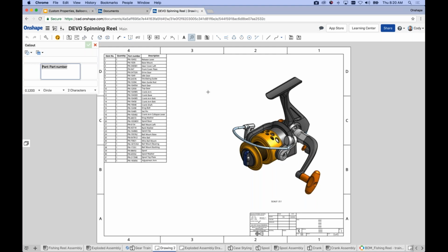And so by default, when you click balloon, right, the callout command, you'll see you can define what you want it to be, right? So I can go in and define item number, for instance, and define that as the criteria that I want for my callout. Now, you may have seen part number or description or revision, right? It really depends what your goal is there. But then from there, it's really just a process of left click, left click, left click. And all I'm doing is left clicking to define where the attachment point of my balloon is, moving out, left click to actually place the balloon.